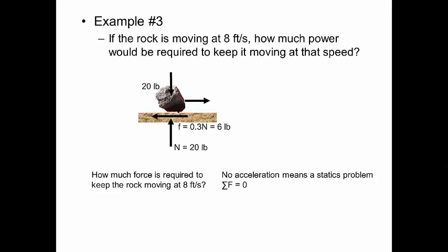There's no acceleration, we're going at a constant velocity, so this means that it's a static problem. The sum of the forces equals 0. If the sum of the forces equals 0, then looking at the forces in the x direction, the force that's being applied is 6 pounds.